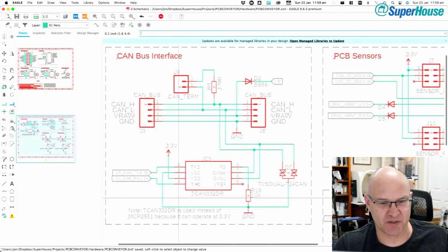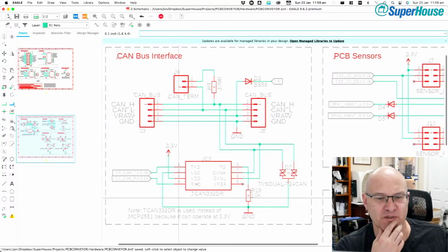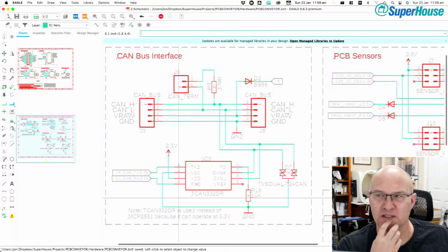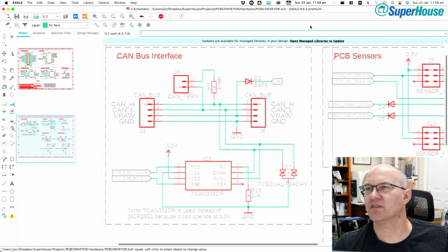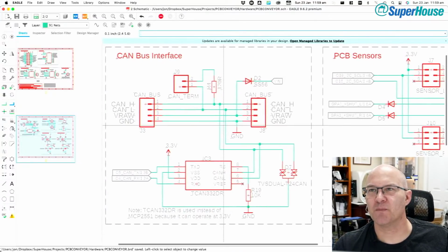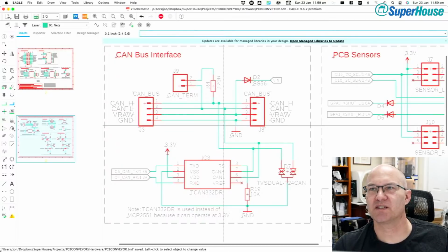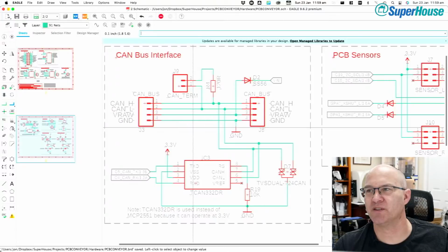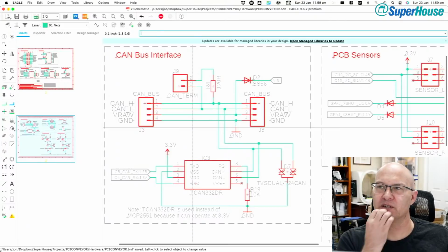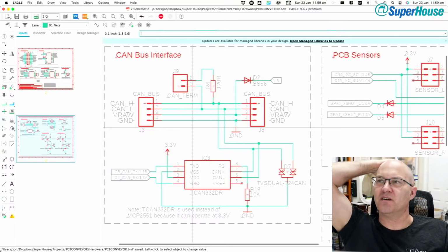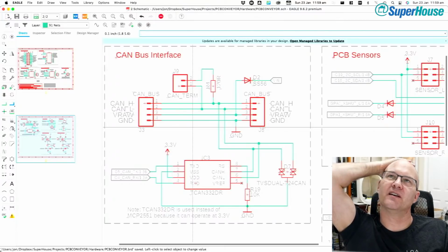I'm only limiting to 1.2 amp. Sion says, datasheet says up to 3.6 amp, but not sure I trust it. Johnny asked, can you put those in parallel? Putting things like power switches and MOSFETs in parallel to increase their current capacity is actually kind of dangerous. There are some hidden traps because of the way they work.